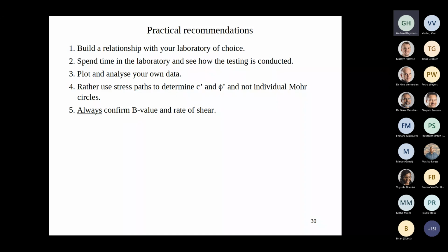I am not in favor of multi-stage shear testing. And again, you don't need 20 years experience in a lab to come to the conclusion: why would you even bother testing a failed specimen? I mean, seriously. To me, just from a sanity viewpoint, it makes no sense. So fail a sample and reconsolidate again, and then fail it again. I mean, what are you now testing? So I just bluntly refused.